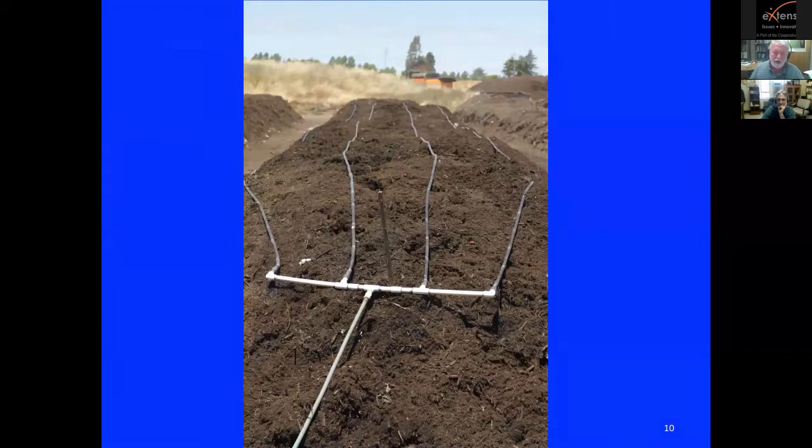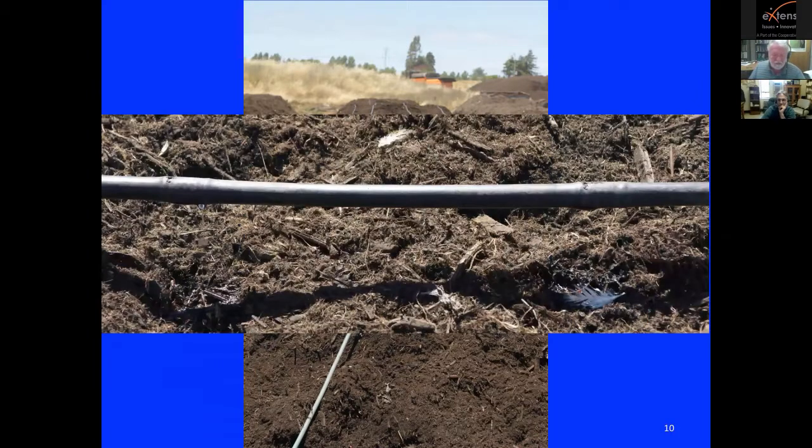This is another way to add water. It uses irrigation. These pipes have emitters in the pipe themselves. If you look at these little spots along here, the spots on the pipe are probably an emitter. We'll look at a closer view of that in just a moment. This is drip irrigation, and this is done at the Sonoma compost site also. These emitters, which you can see 2 of here at the 2 extreme sides of the pipe, put out about 1 gallon per hour. And you can get them in 1/2 gallon, 1 gallon, 1.5, and 2 gallon outputs.